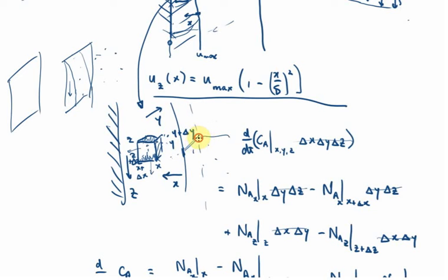And so if we have the mass transfer coefficient out here and so on, we can estimate the difference between this bulk concentration and that surface concentration. So we can eventually determine a surface concentration here. That's one. And that applies only on the gas side, remember. We still need some equilibrium difference between the gas and the liquid, right?